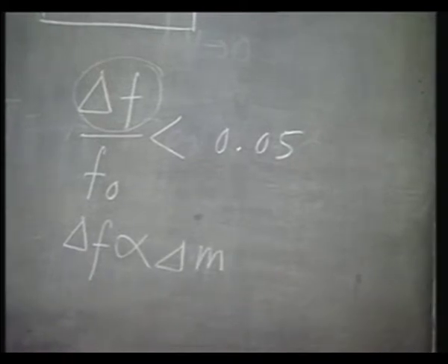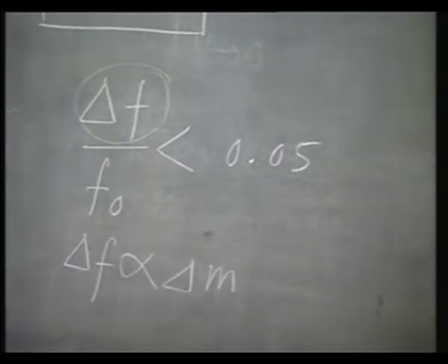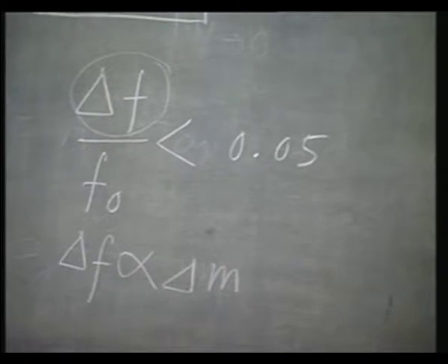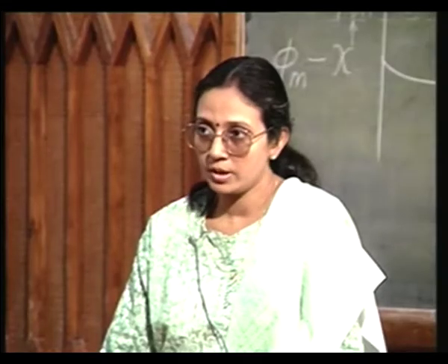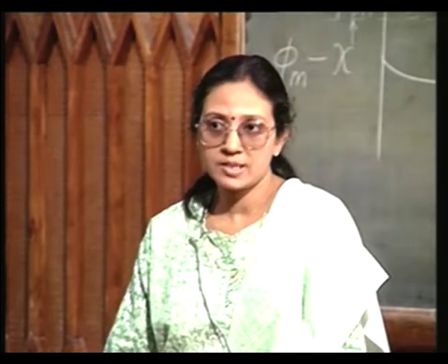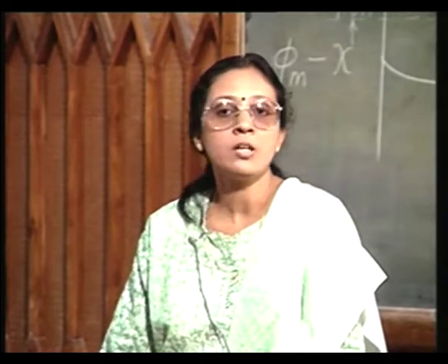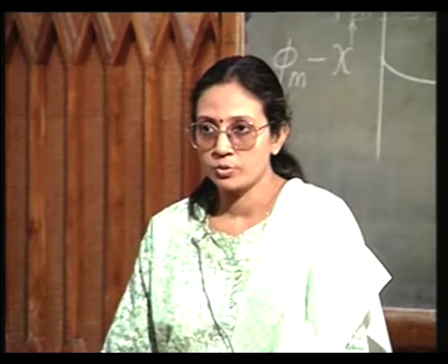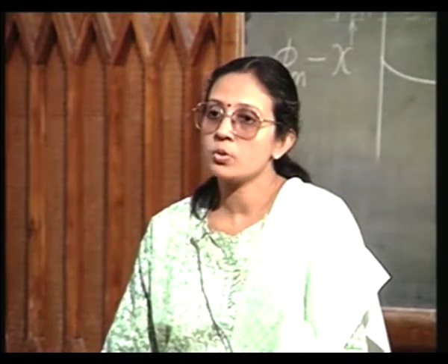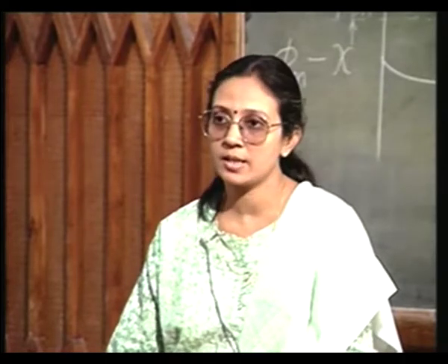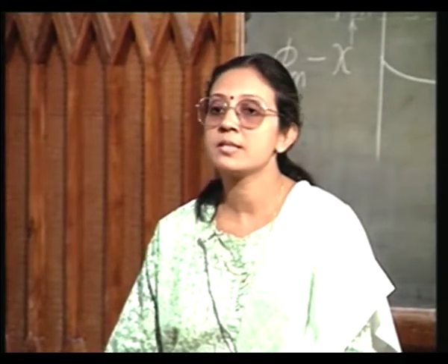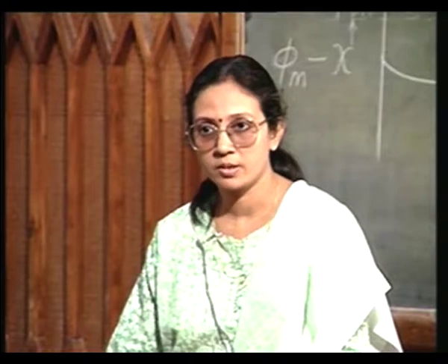Do you understand? I have kept the quartz crystal at the same level as the substrate. So, while the substrate is getting deposited with the metal film, the same amount of deposition is there on the quartz crystal also, and this deposition is going to alter its resonance frequency. I have an electronic circuit in order to find this change in the resonance frequency.